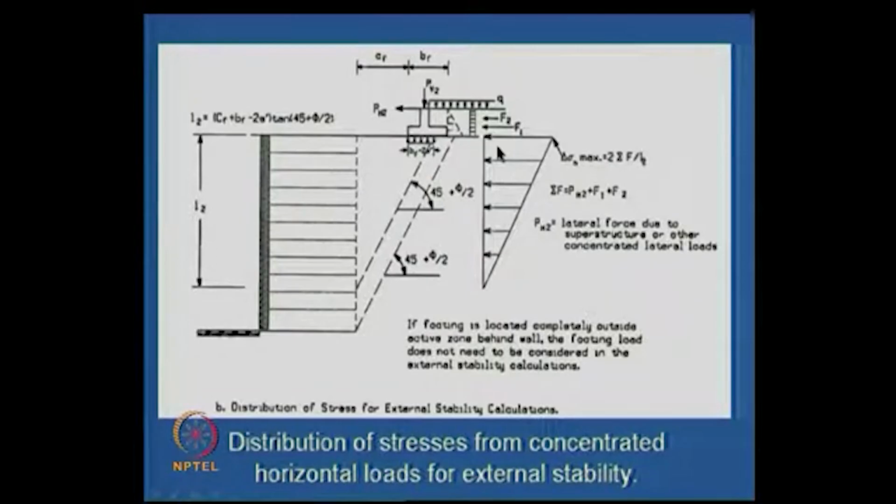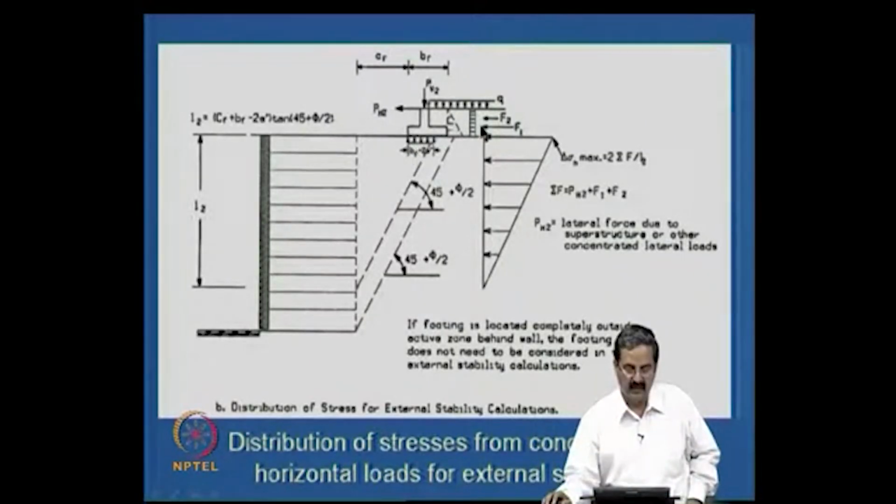There is another case where your RE wall is on a curvature. There could be some horizontal force acting like this. What you saw was a vertical load, and even for horizontal force, one can completely check this. They have some appropriate formula for this: what should be the lateral force that one can expect when you have a thing like this. So, that is also possible.